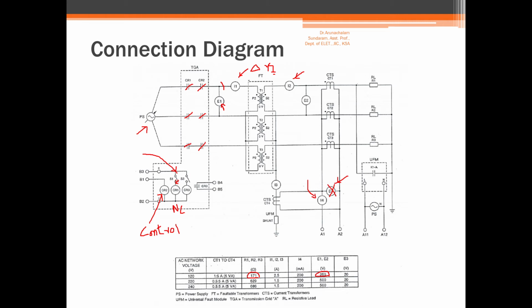In the second part of the experiment, we are going to use over voltage protection, so you should not connect the ammeter. This point is very important. Even though they have given you a single connection diagram, we are going to work with two relays, one overcurrent relay and another one, an overvoltage relay. So we have to be very careful while we are connecting.